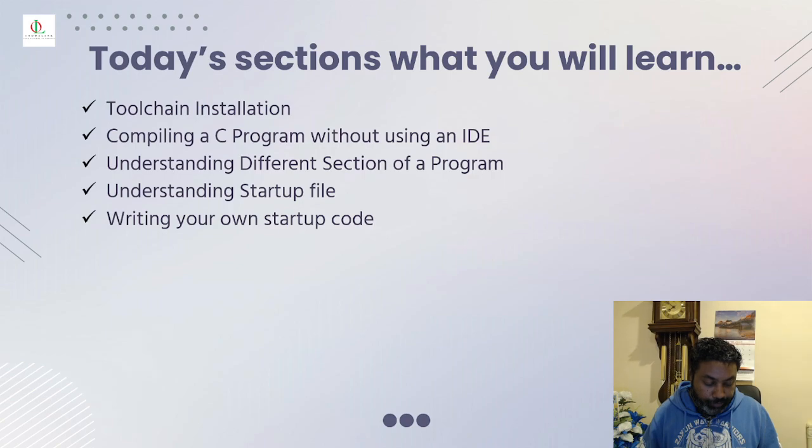general IDE. So you're going to learn again how to compile a C program without using an IDE and learn about different sections in the IDE, but in a much more detailed version about what each and every section represents. And also you're going to learn what a startup file is and how these sections are placed inside the microcontroller memory.